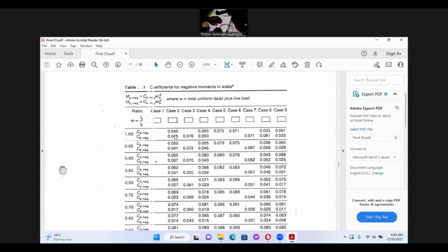And this is a square one. This is square, and these are rectangular ones. And here you can see the a direction is the shorter direction. In the shorter direction, a huge moment is carried. In the longer span direction, a smaller moment is carried.